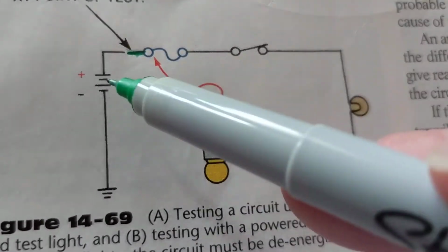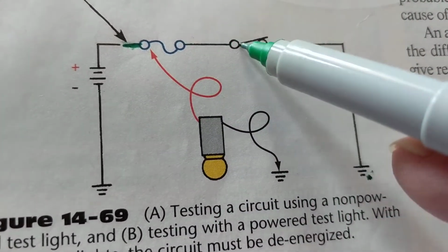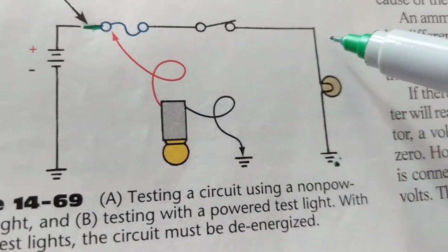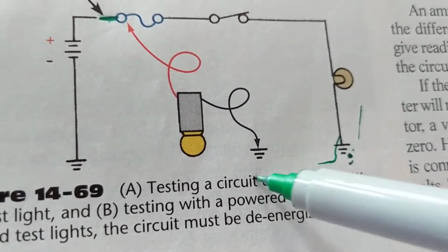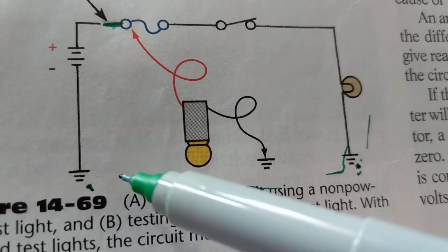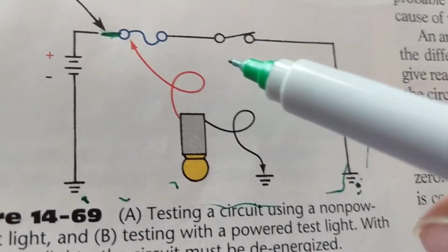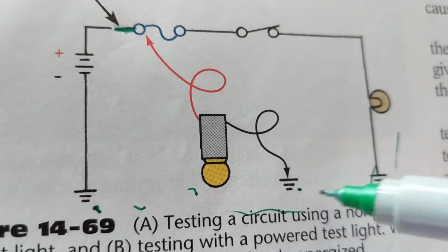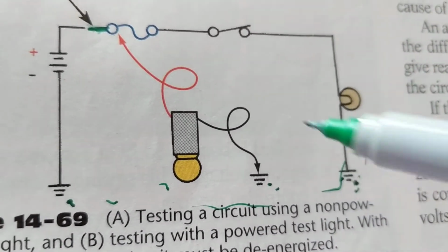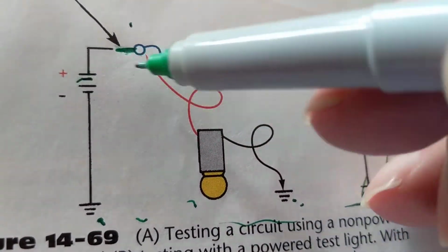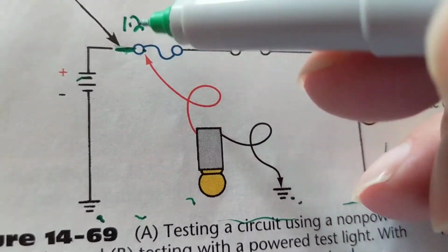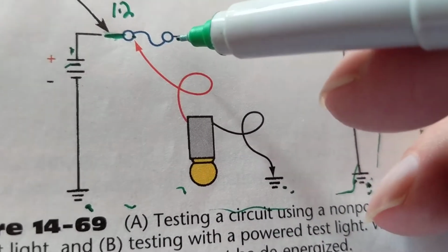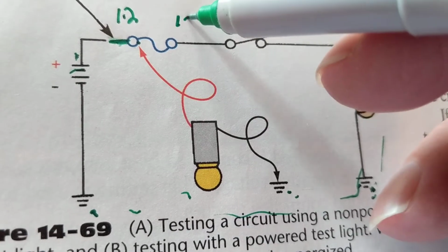Now let's go over here. Current flows, conventional current flows here, here, into the fuse, out of the fuse, into the switch, out of the switch to a lamp to illuminate that light. Now, if you want to check the fuse, what do you do? With respect to ground, you go to here. One side should be what? 12 volts. That we always say. Why 12 volts? Because it's connected to the battery. What should be the other side? Just a piece of wire should also be 12 volts.